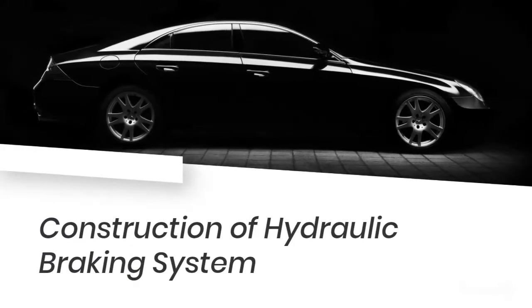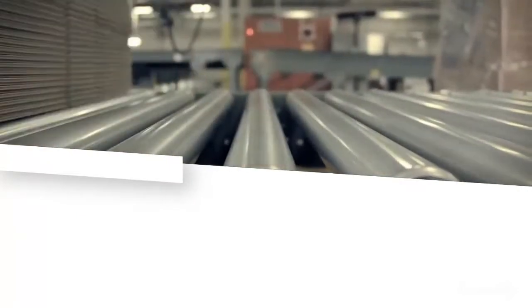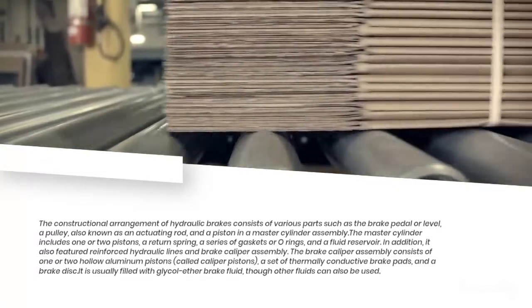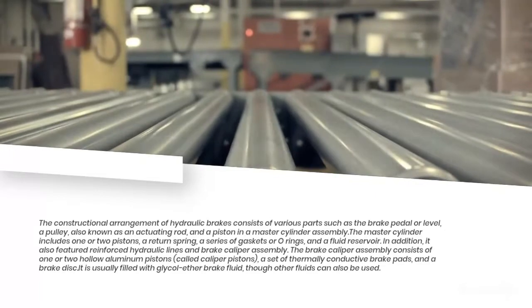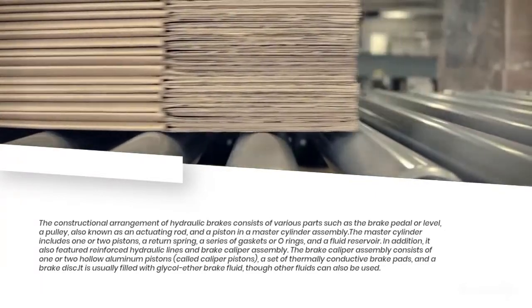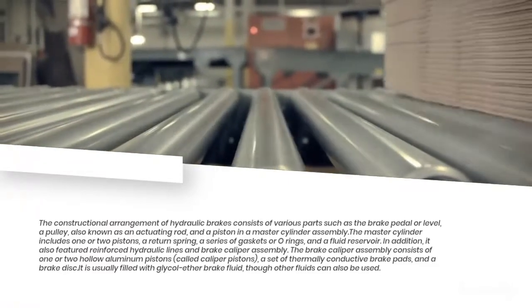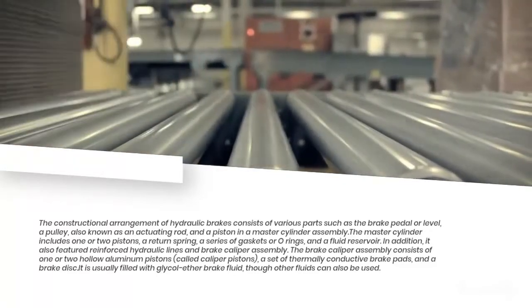Construction of hydraulic braking system. The constructional arrangement of hydraulic brakes consists of various parts such as the brake pedal or lever, a pushrod, also known as an actuating rod, and a piston in a master cylinder assembly. The master cylinder includes one or two pistons, a return spring, a series of gaskets or O-rings, and a fluid reservoir. In addition, it also features reinforced hydraulic lines and a brake caliper assembly.